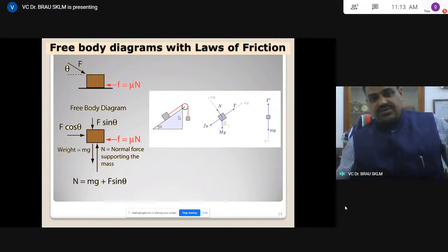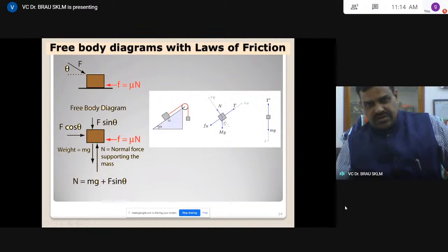Now here I am assuming that it is moving downwards, and with this moving downward, obviously the other is moving upwards and the frictional force is acting downwards. And the tension in the string T. This is a reactive force. And the weight Mg, with capital M and small m. Because the angle between these two is alpha, for this surface this is perpendicular. That's why this angle is alpha, and this is also alpha. There are four forces: frictional force, normal reaction, weight, and tension in the cable.